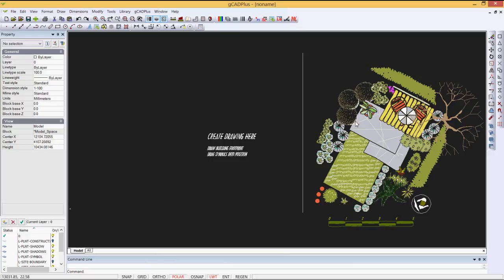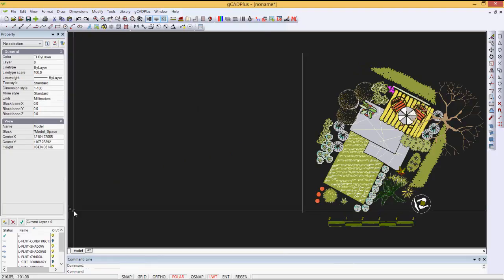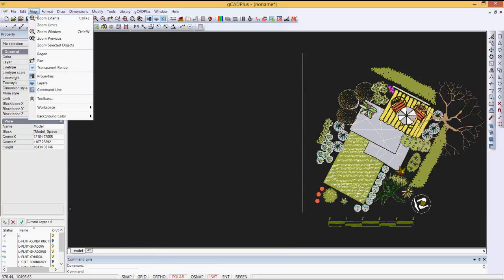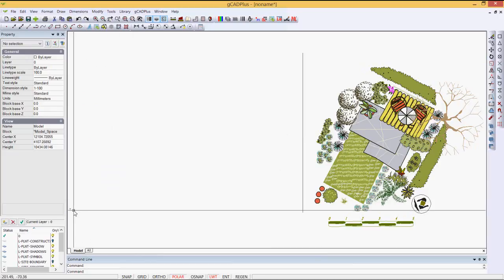Let's run through the steps you would need to take to put this rectangle representing a design space that's 5 meters wide by 3 meters high. First step is let's remove these pieces of text. This point down here, you may be just able to see a dot there. What I might do is just change the view workspace background color to white here so that you can possibly see that dot a little more clearly.